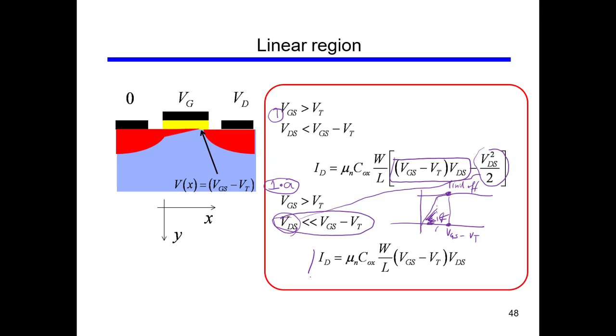That's why in the linear region you have this equation, and this is the same equation that we saw earlier when we were dealing with the linear region separately. So you see that the equation in the triode region that we derived in this lecture is very generic. From that you can reduce to the saturation equation and also the equation for the linear region.